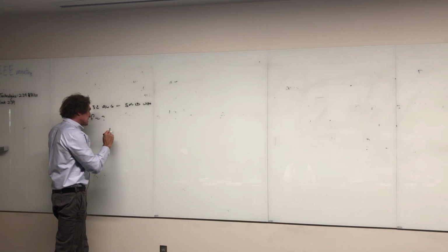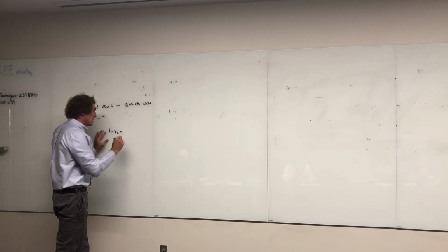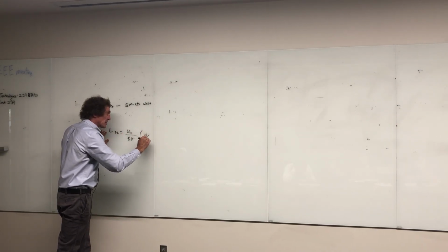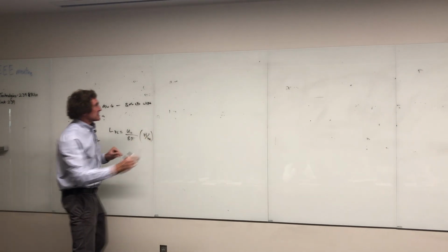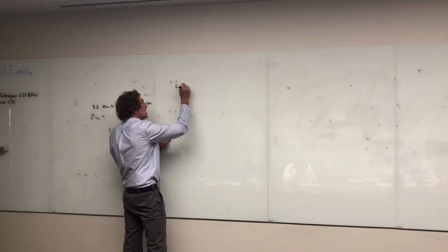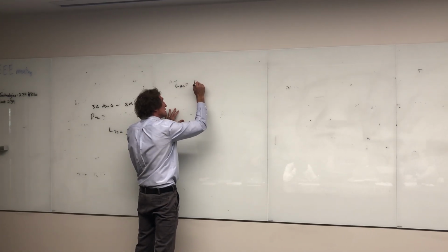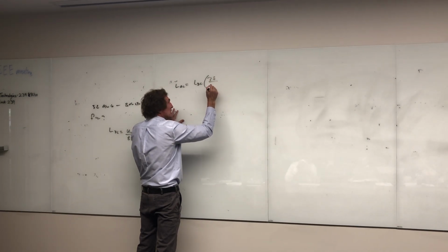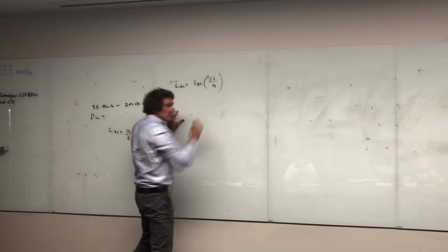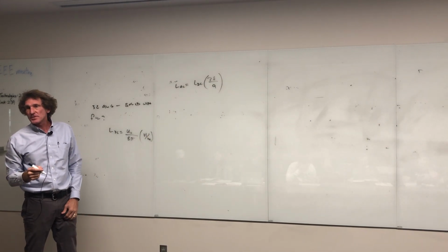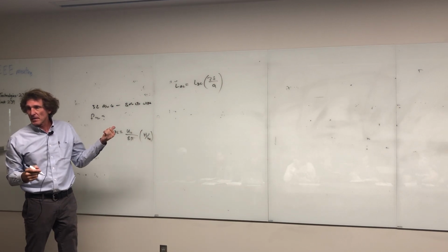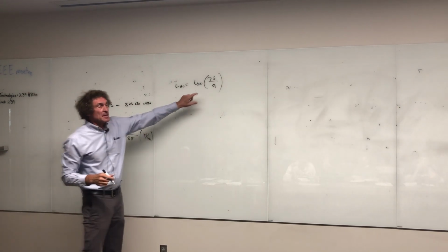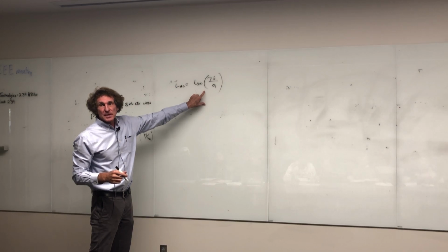Now, the DC inductance is equal to simply mu 0, or really mu over 8 pi, and that's henries per meter. That's DC, right? The AC inductance is equal to what? L DC, the DC inductance, times 2 times skin depth divided by what? The radius. Do you remember this one? That's the formula I gave you. Wentworth gives you a slightly different version of this. This one's easier to remember, in my opinion. Now, you're trying to find the frequency when all of a sudden this becomes important.